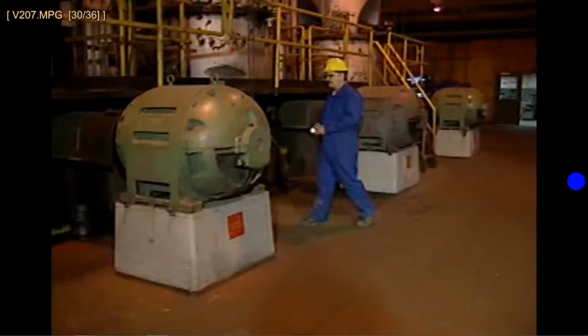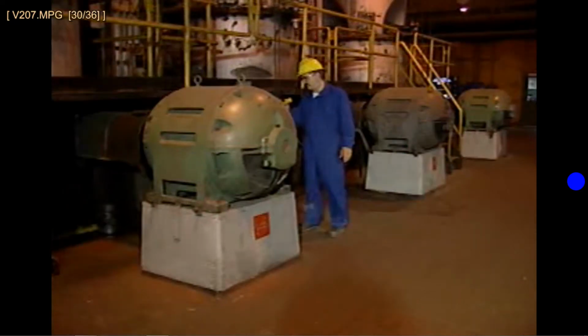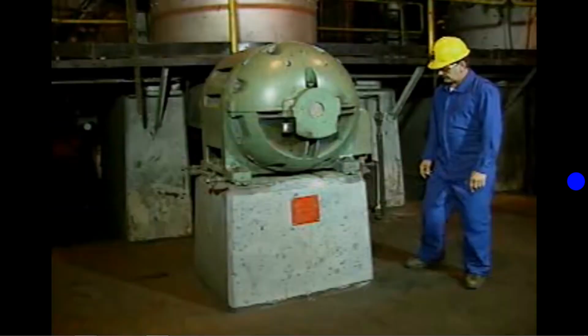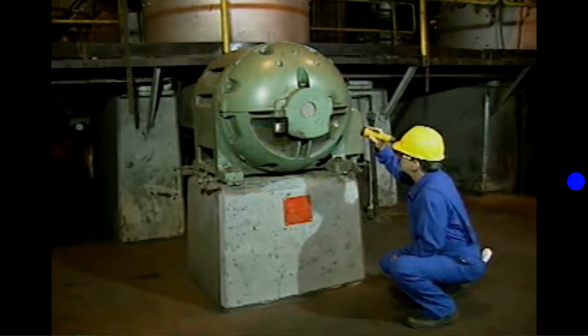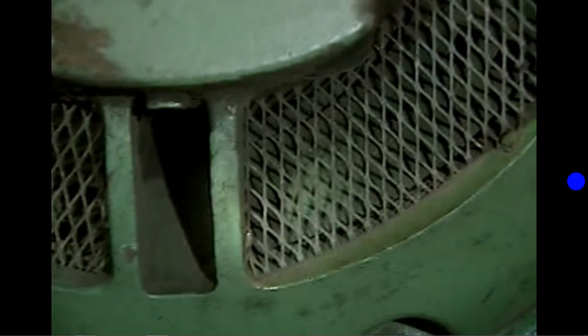The last component to be checked in this motor branch circuit is the motor. First, the motor's ground wire should be checked to make sure that it's secure. Then, a visual inspection of the motor should be made for loose or damaged parts. The motor's opening should be checked to make sure that there is no unusual accumulation of dust or any obstructions. The openings provide the motor with a means of ventilation for cooling, so they must be kept clear.